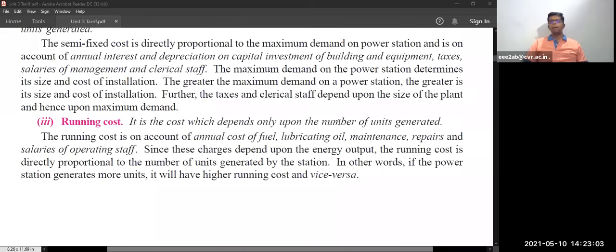Everything has to be maintained frequently. But if you see, government owned ones are maintained after 6 months once or 3 months once. But the rule is that 30 days once, per month, they have to come and maintain, test the viscosity of the oil, then feeders, transformers, everything.